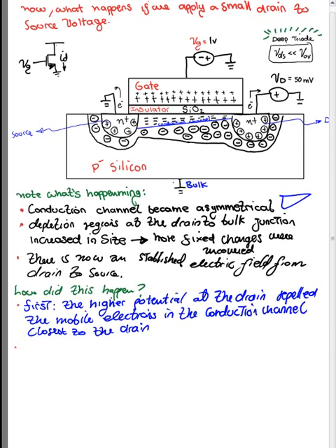The second is what I explained before, that since a higher potential was applied at the drain, VD, more electrons left the N plus material, leaving more positive fixed charges uncovered, widening the depletion region. So let's write that down.